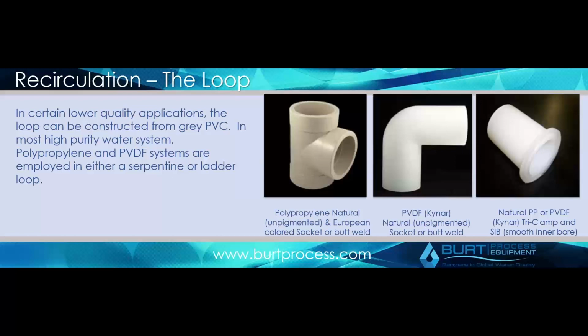And if you're talking about a higher level bacteria requirement, you want to sanitize probably several times a year. In the bacteria field, they'll do sanitizations every day because that's how critical bacteria and endotoxin buildup is in that various industry. And the sanitization process, the system is generally still running. You just bypass your DI lights and bypass your DI bottles, and essentially the water is a low concentration, maybe like a 2 ppm level of ozone overnight, and then the UV lights are turned back on, and it basically just turns the ozone back into oxygen at that point.